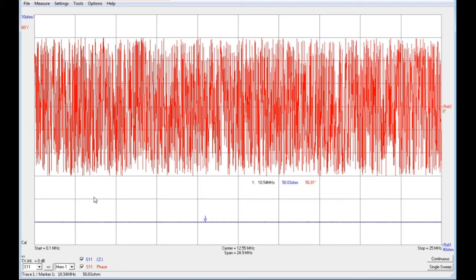Now, obviously, we would normally expect a phase transition of this to be plus 90 and minus 90 in the imaginary. But this VNA considers the whole 360 degree rotation. So phase is displayed as a plus 180 and minus 180 transition. So here the phase is just whipping round as the perfect match. Nothing is reflected back, so there is virtually nothing to measure that comes back into the reflected mixer, and therefore the phase is just flicking backwards and forwards between plus 180 and minus 180. That's characteristic in a vector network analyzer of a near perfect match.